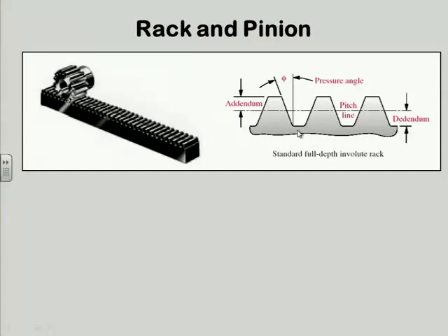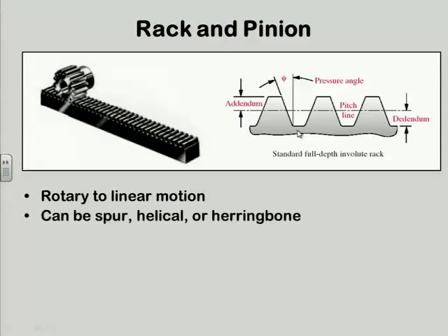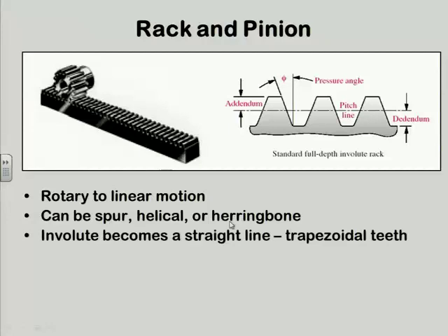And in the process, I get nice-looking teeth which have a true involute because I'm generating them with an involute, which now you can see why, if I have an interference problem, I'm just going to remove the material in the process of making the tooth, right? Because this is a true involute all the way to the tip. That's going to go in there and eat out the root if my pinion's too small for the size of the teeth and so forth. So I'll never see the material that would interfere on a physical gear because I took it out when I cut it. And I can use either spur, helical, or herringbone types of gear shapes on this thing.